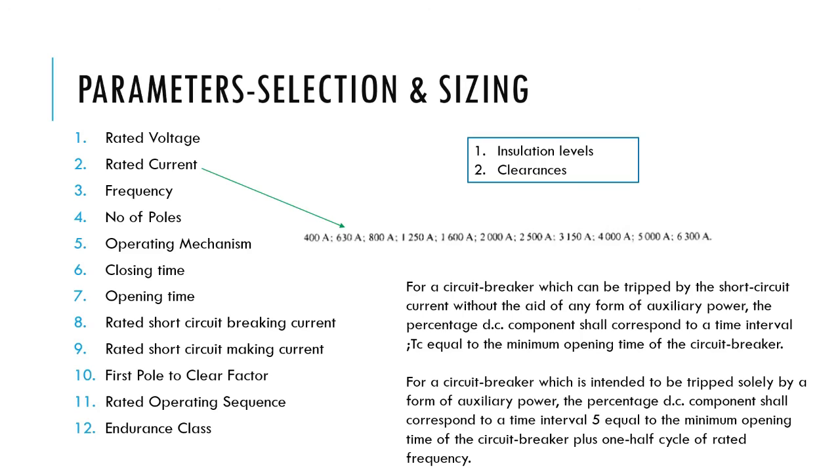So I will adopt some kind of functionality called auto reclosure. We will see that in the next points. For that functionality, only that pole has to be operated for which the fault has occurred. That pole operates, and I am again closing it. Let's see that in the next topic.